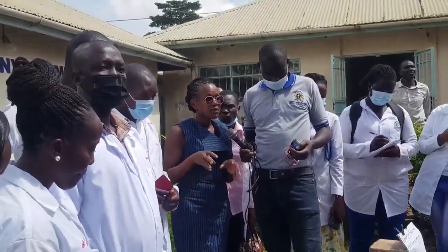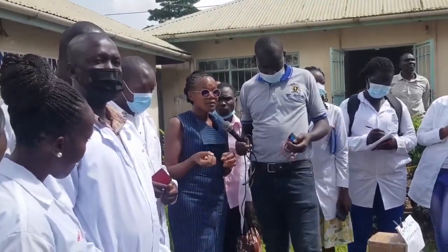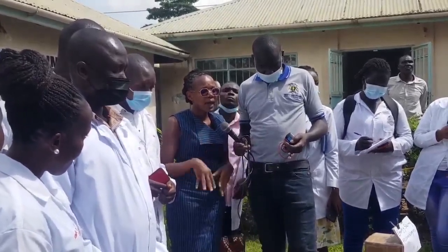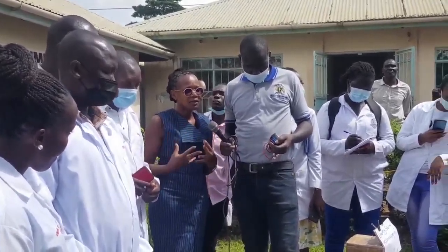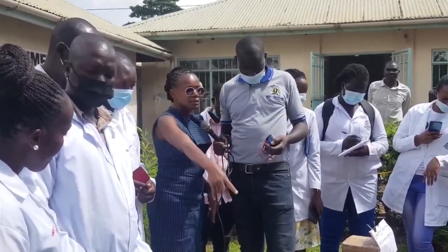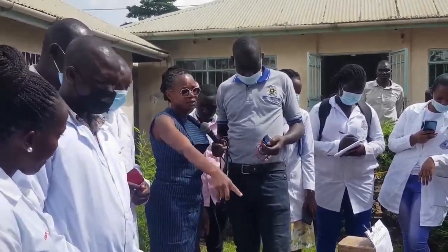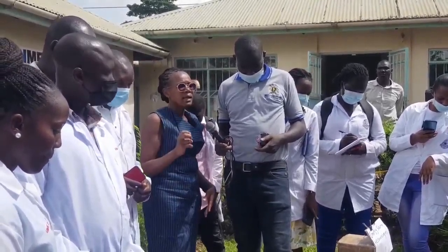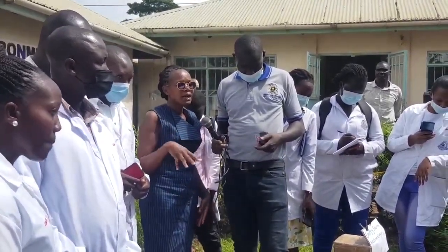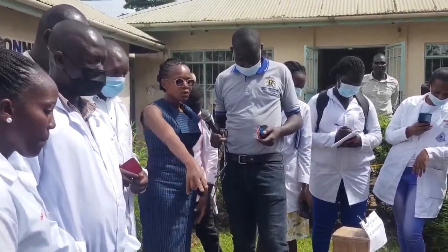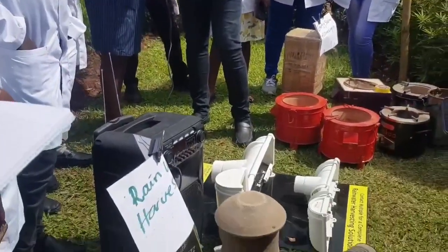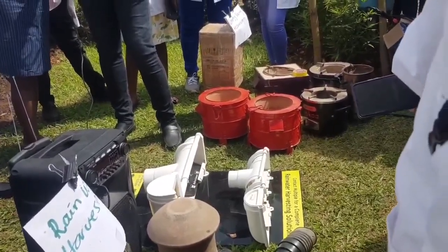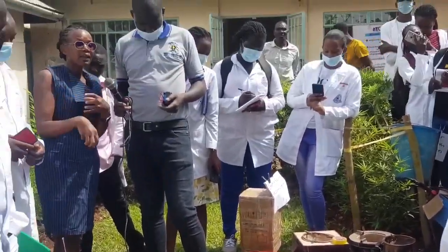So we have come up with different technologies or devices that can be used to enhance the quality of rainwater. And this is what we call the first flush device. The rain filter is in the category of the first flush device, that it flushes off the first foul water before the clean water goes into the tank, to minimize the silt. But also the trap helps you to trap the crawling animals, the leaves and some solids that would have ended up in your tank.